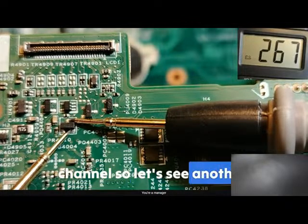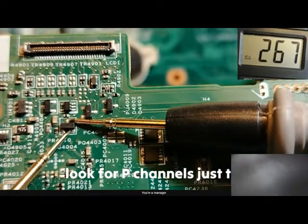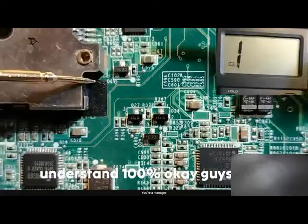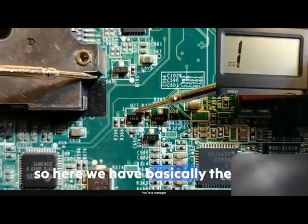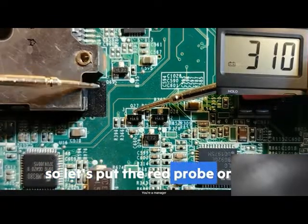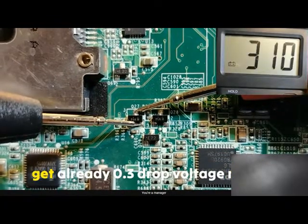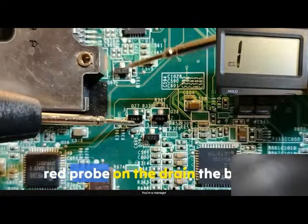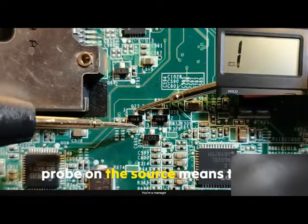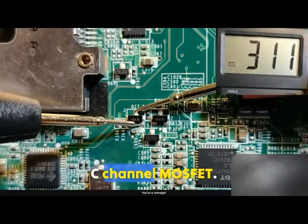So let's see another motherboard and look for P-channels, just to understand 100%. Okay guys, let's check this MOSFET over here. So here we have basically the drain. So let's put the red probe on the drain, the black probe on the source. We get already 0.3 drop voltage. Means what? The red probe on the drain, the black probe on the source, means this is a P-channel MOSFET.